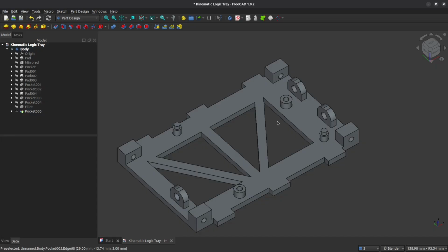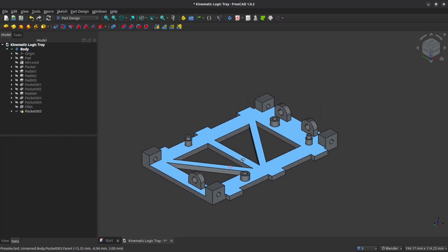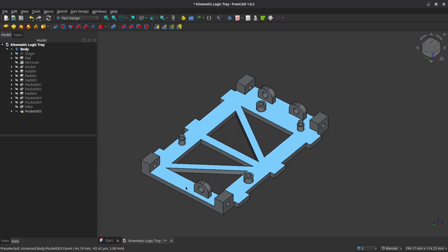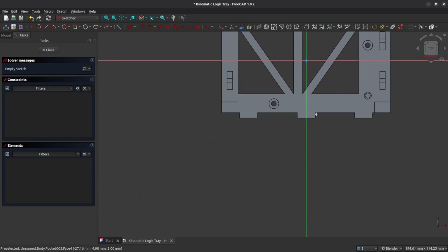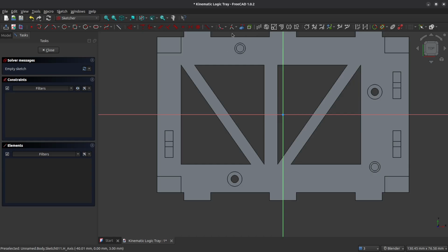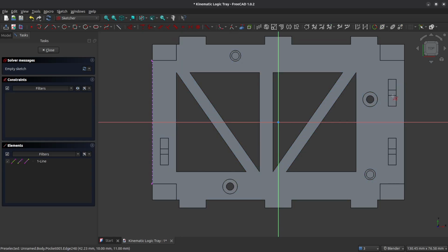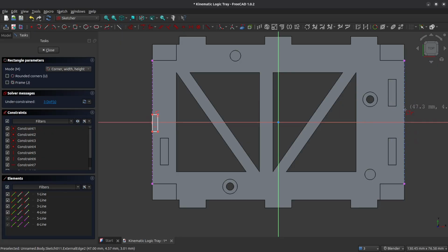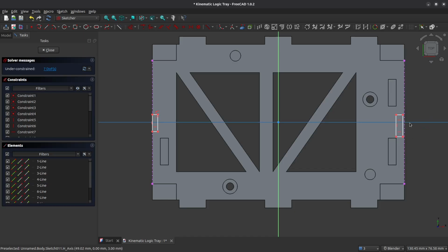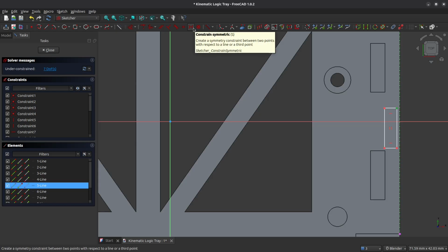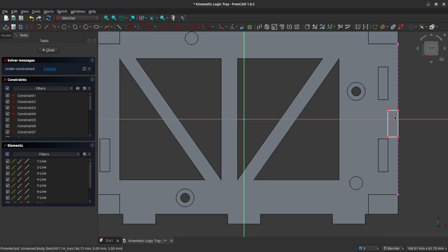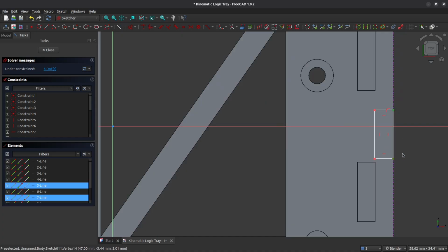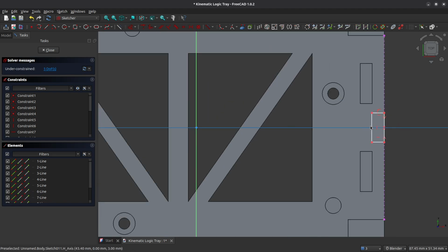And the next thing that we need to do is add a couple of shell anchor points on the edges of the trays. We will later on add door panels and attach them at these points here. So we're going to reference the left hand and right hand edge of the tray here, and we're going to grab the rectangle tool, and we'll create 2 rectangles that we will make symmetric to the x-axis. This one never got attached to it, so we will make it coincident there. And we will set it so that it is symmetrical. All right, so there we are.